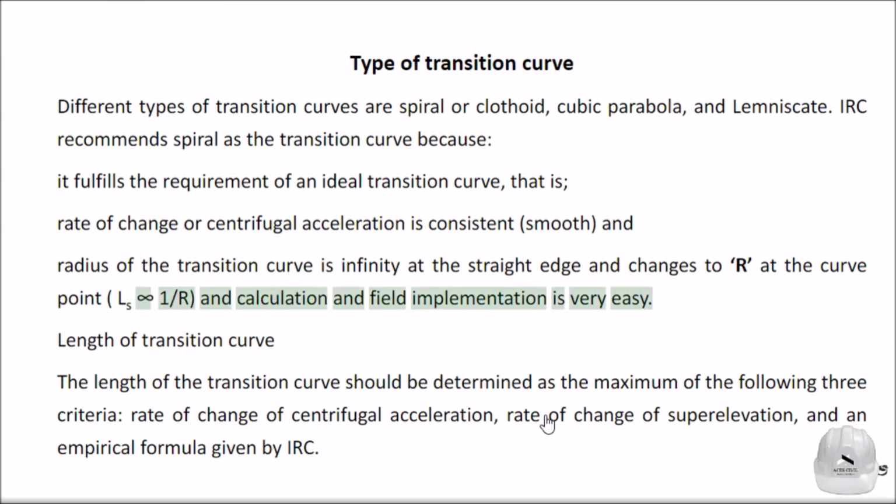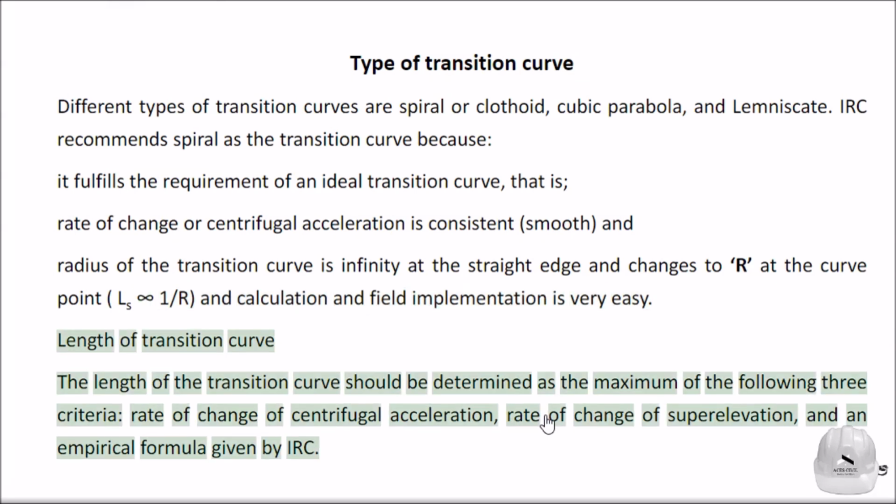81/R, and calculation and field implementation is very easy. Length of transition curve. The length of the transition curve should be determined as the maximum of the following 3 criteria: rate of change of centrifugal acceleration, rate of change of superelevation, and an empirical formula given by IRC.